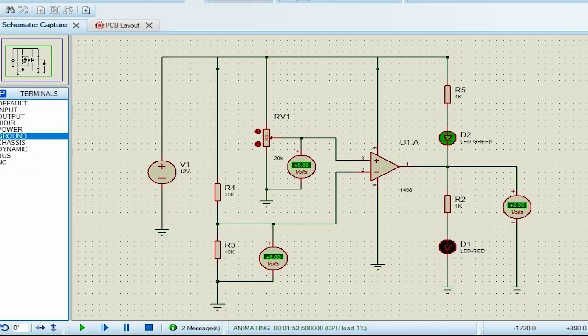The output voltage is not exact, because we are using the operational amplifier only as a comparator, without any resistive component connected. In this case we are using 12 volts, but if we connect it with a symmetrical source it is going to be exactly equal.